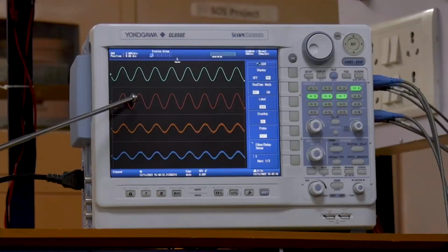We can see from the DSO waveform that the currents I21 and I22, that is the third and fourth signals, have high frequency oscillation due to the presence of interactive components. The frequency of oscillation is equal to the resonant frequency of the LCL filters. Moreover, the total grid injected current of channel 2 is stable. These two test results are in tandem with the analysis performed in this lecture. Thank you.